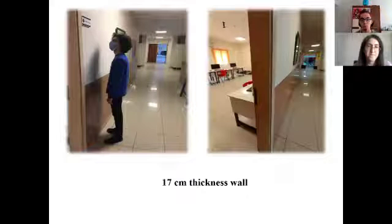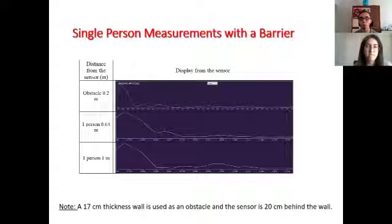The measurements for 1 and 2 persons, which we measured using the 17 cm thick barrier, are shown here. We positioned our obstacle at a distance of 20 cm from the sensor. We can say that as the barrier thickness increases, the signal loss increases in the measurements.